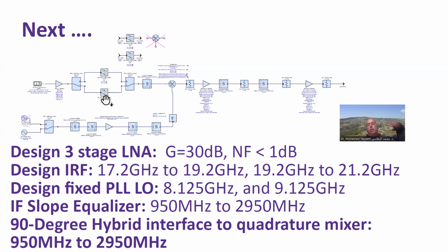So really, to counteract this downward slope, because this chain deteriorates in frequency, the gain as a function of frequency goes lower and lower as frequency goes higher. We need to undo that, and the way we do it, I'm going to have a small passive section in here that, if the gain is going this way, that one will be going this way, so that overall there is equalization of the gain as a function of frequency.